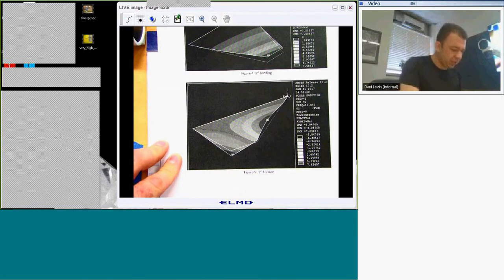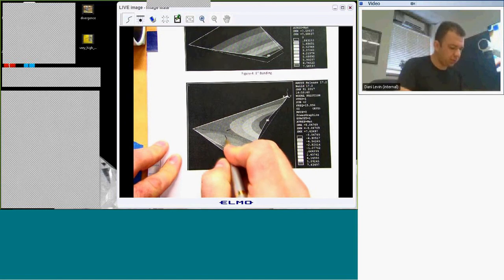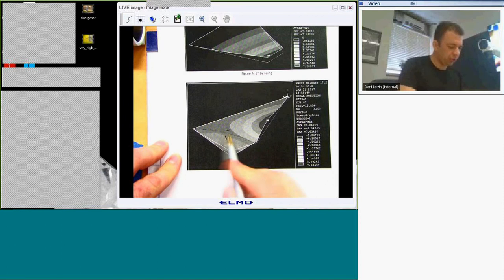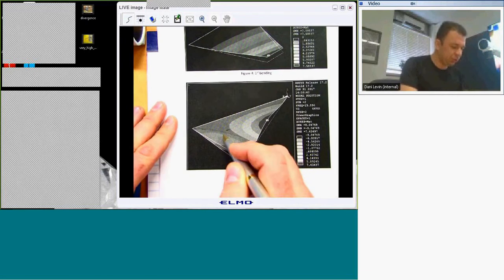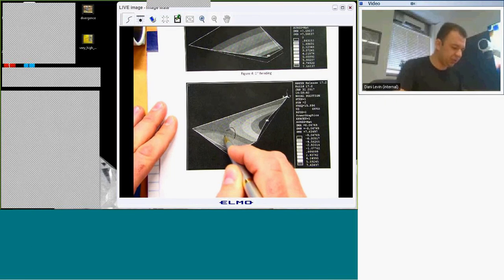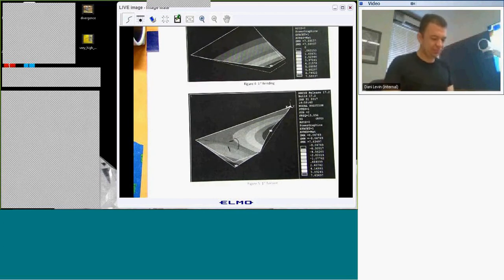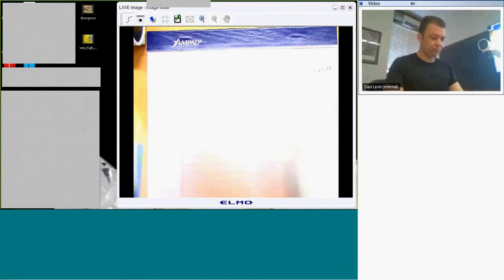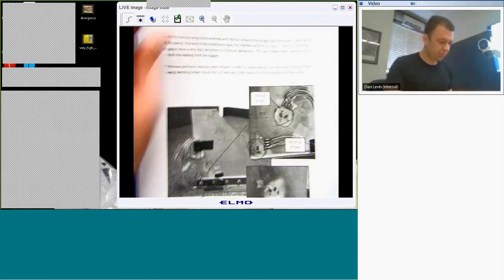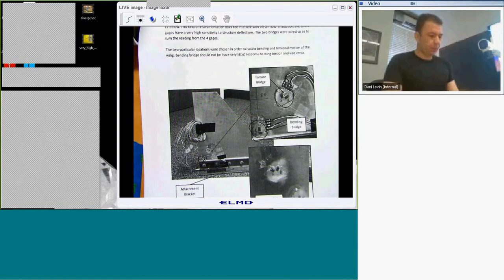So what I did, I put gauges in these locations. In this mode we have no bending, and we wanted to sense, to measure only the torsion motion. So around the nodal line should be the better location for this mode. Here's a case that's not flutter, of course, but here you have the eigenvector of your structural modal analysis, and from that you can find the shape of the mode in which the plate is vibrating.